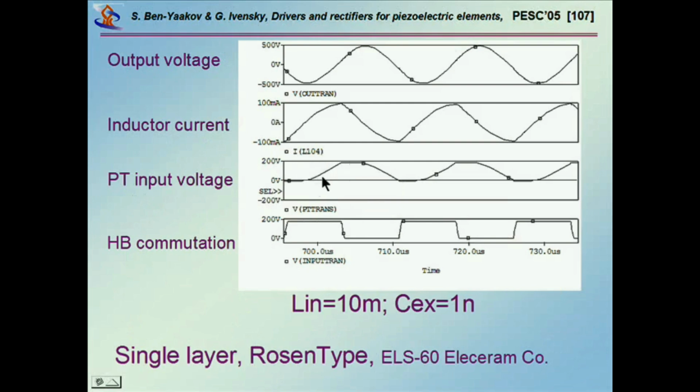You see here, this is the voltage, and what happens is that the sinusoidal wave is building up, and then it is clamped to the bus voltage and then to ground. So you do have limitation of the voltage. You are not afraid that you'll get very high voltages, and of course you can adjust it to be in the area that you are interested. In this case, you have a nice inductor current, and of course, soft switching. So this is a possible solution.